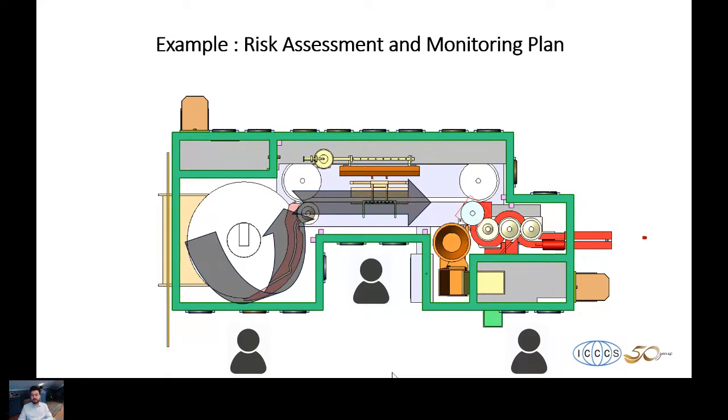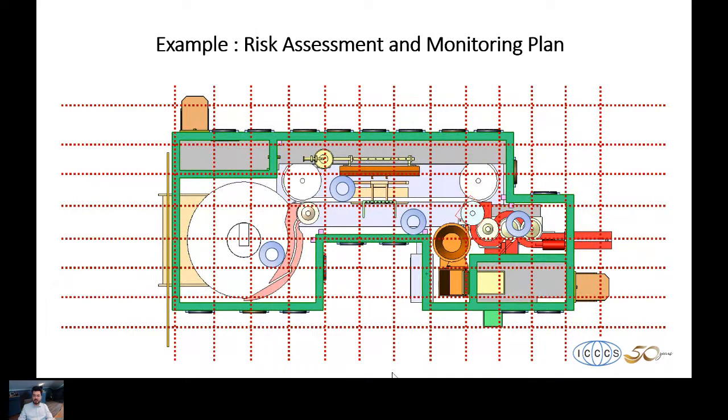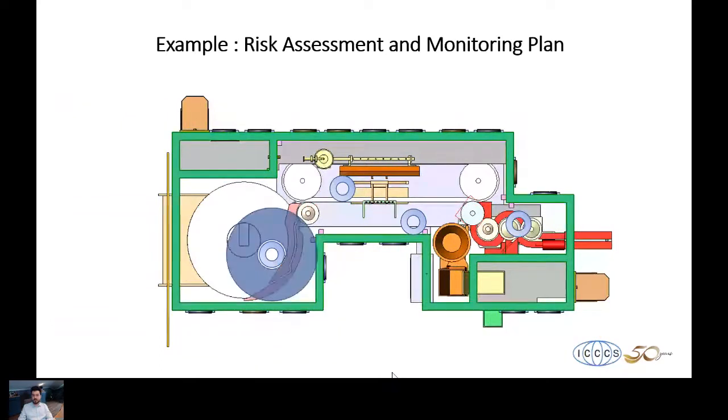And we send them directly into the filling line to the needles. And after stoppering or semi-stoppering, we are sending them to the exit of our filling line. So if you take a look at this, our risk points during this process will be these locations. The first one will be covering our turntable on the accumulation side. The second one will be covering the needles on the left side most probably.